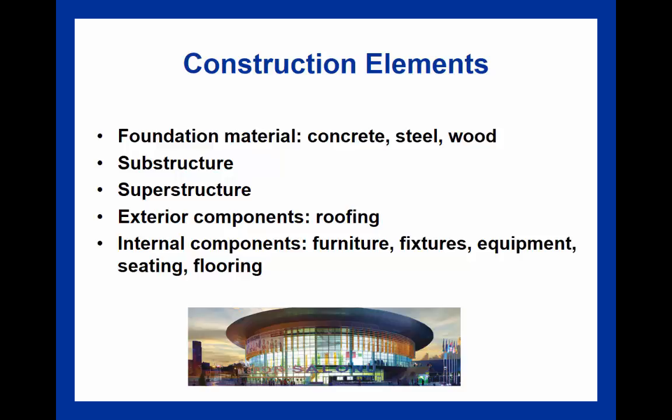A facility, before construction occurs, might need to grade the different elements of that land so that different dips or hills or irregularities of the topography can be uniformly graded, so that you've got one flat surface where the facility can be built. So raising or lowering that proposed site can take up time and money, where the contractor might need to use bulldozers or excavators or even excavate by hand. So this could be a comprehensive process.